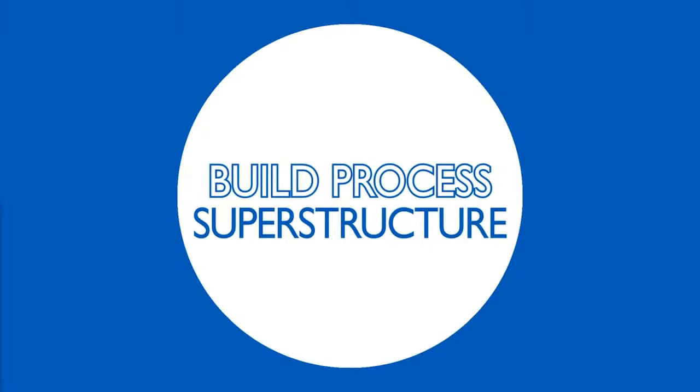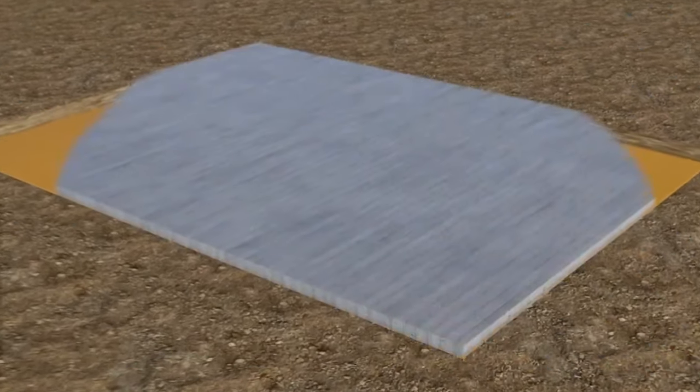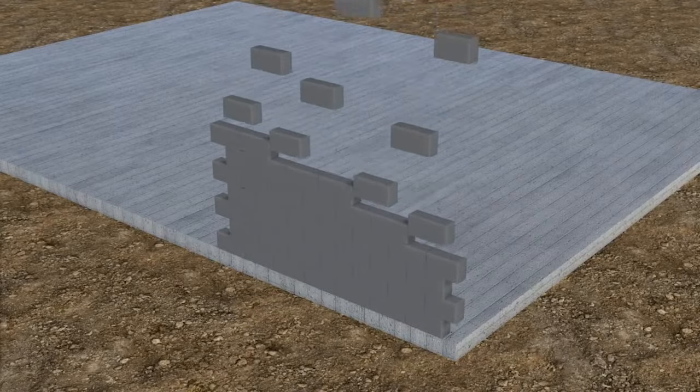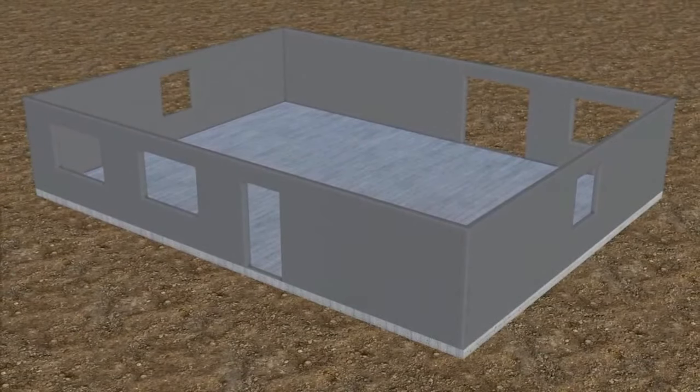The parts of the building above the foundations are referred to as the superstructure of the building. In traditional build, the upper parts of the house are made from brickwork and concrete blocks, with floors either being beams and blocks or timber joists. Homes of this type are constructed wholly on site, and this can be a relatively slow process as brickwork and blockwork takes time to lay, and concrete and mortar have to dry out and harden before additional works can be undertaken. As we discussed earlier, this slower process and higher level of wet trades means moisture loads may be a lot higher and must be carefully managed.